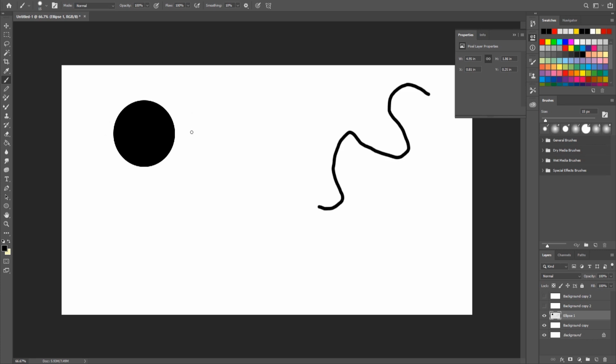And right now this is a closed curve, so we're going to create points on the points that are already created, and then we're going to open it up. So we're going to create a second point on the very first point. So we actually can open it up, and we have the same ending part and beginning part,